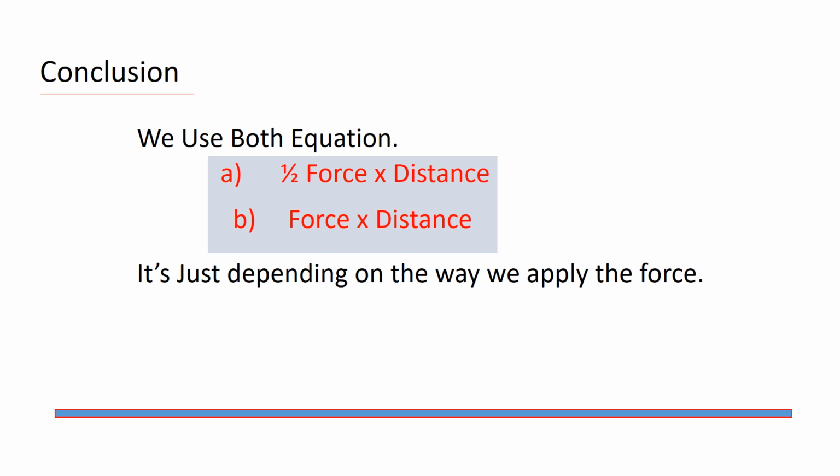It's a rotation. It has no unit. It's not degrees or whatever. So we still get a kilonewton meter. Since rotation is effectively unitless, we get moment times theta rotation as the work done.